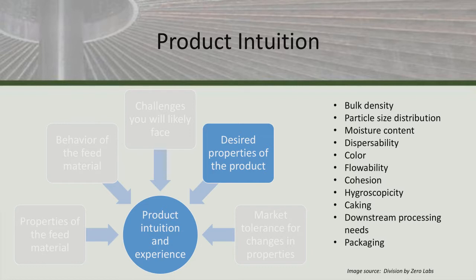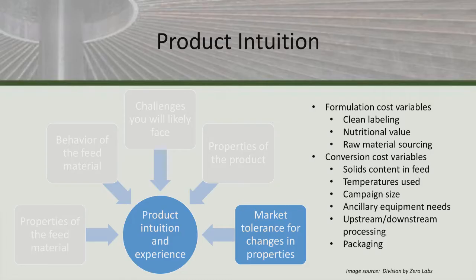And you would address this by looking at cohesion, hygroscopicity, and caking. And finally, are there any downstream processing needs? Just like the upstream processing needs, if there are needs, you may have to provide that equipment yourself. And then this is the most important one, in my opinion.